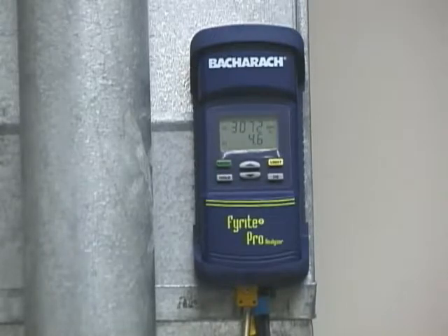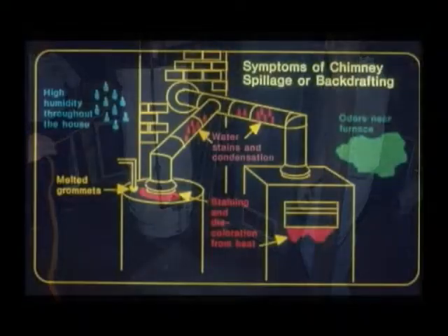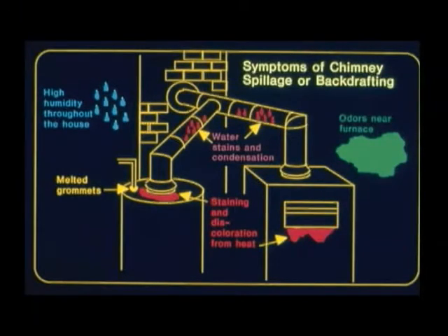If the spilled combustion byproducts that didn't vent get drawn back into the burners, these contain a high carbon dioxide level and low oxygen, which causes incomplete combustion and creates carbon monoxide. While most Category 1 appliances will spill for up to a minute on startup until the vent gets hot, many will spill for up to 3 or 4 minutes at the start of most cycles. Since many furnaces may only run for 5 or 6 minutes each cycle, a very high percentage of the total combustion gases can end up in the living space. This is not healthy and should be remedied.